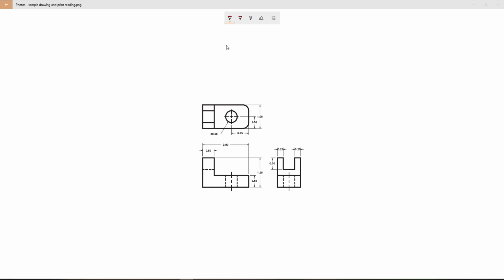As you can see, we have a drawing in front of us, and this drawing has three views. The front view is located in the lower left-hand corner. The right side view is basically looking at this object from standing over towards the right side, and then the top view is looking straight down from the top of the object. These are called the primary views. These primary views are very typical of drawings that you're going to see created.